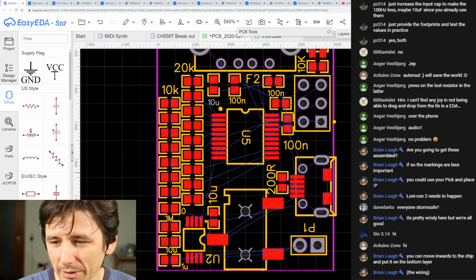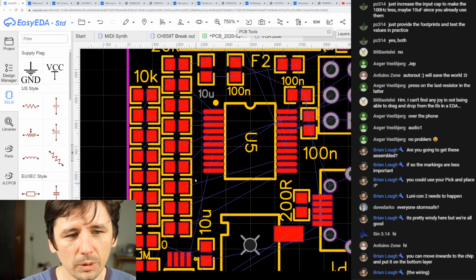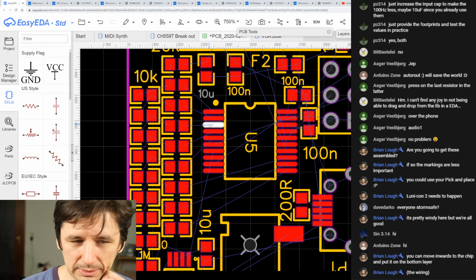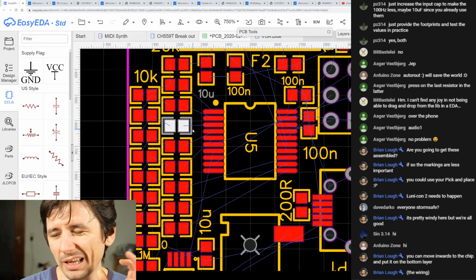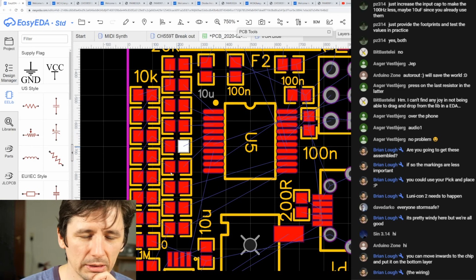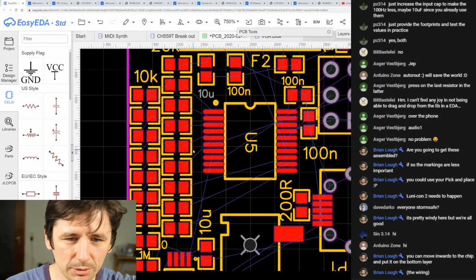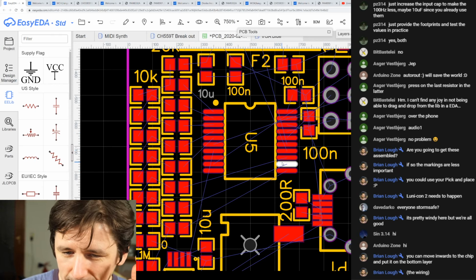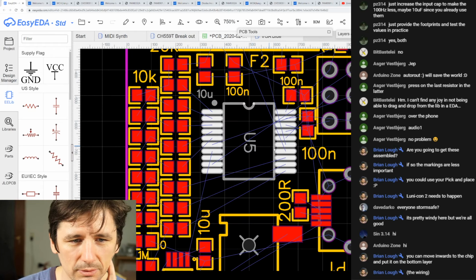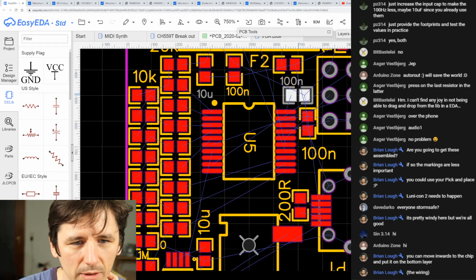The wiring on the bottom layer, what? Yeah, for the audio, I don't want to make any wiring, like avoid additional wires, because the traces should be as short as possible to not induce any noise. So I want to be really tight here, everything. I don't want to have many wires and get, from maybe a battery or something on the bottom, an additional noise source on a single digital audio channel. But this here I could definitely put on the bottom side.